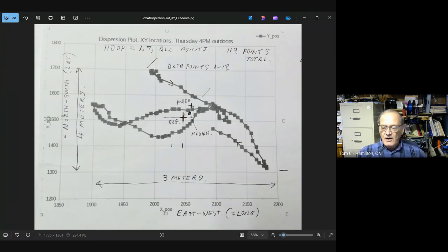Now, on my robot, I take the GPS coordinates that I get from the GPS receiver, and I subtract them from a local origin, a local GPS origin, in order to give me relative numbers. And that's what's graphed here, basically the X and Y coordinates that the robot is reading second by second, compared to the GPS origin data, which had been taken at a previous point in time that same afternoon, but in the same neighborhood. The local origin doesn't have to be in exactly the same place.